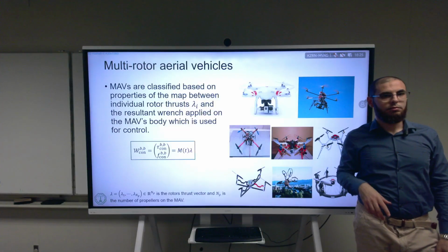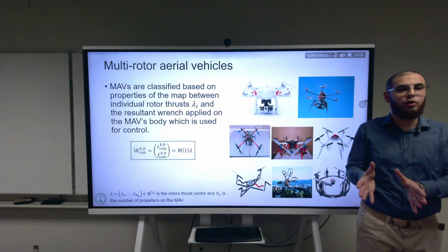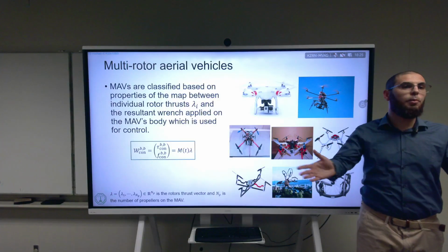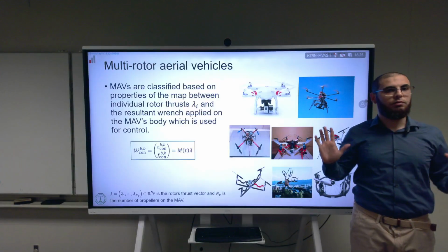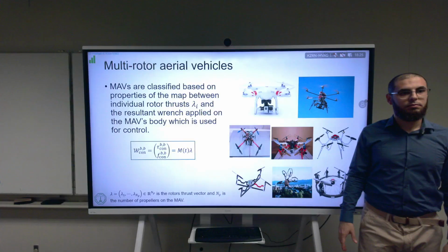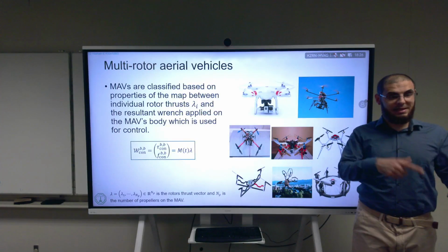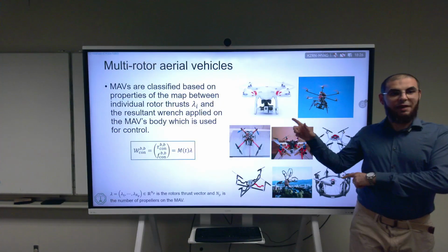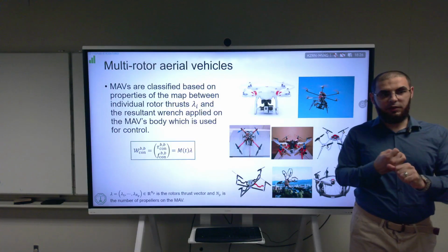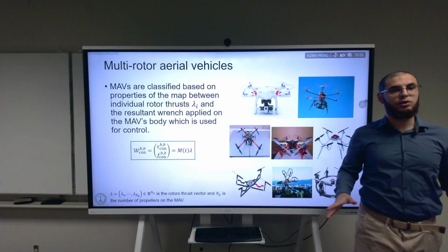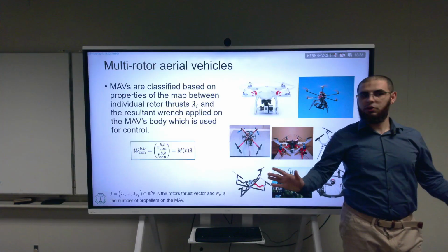Okay. So how do we calculate the KP and KD? These are gains. You tune them. You have so many options depending on the performance you want. You want it to be very aggressive, or very soft. It's up to you. In normal control, we had to calculate KP and KD such that the system is stable, right? We have the conditions here. We said that KP should be positive definite, KD should be positive definite. That's the only thing for stability. Anything else is possible: trial and error, manually.